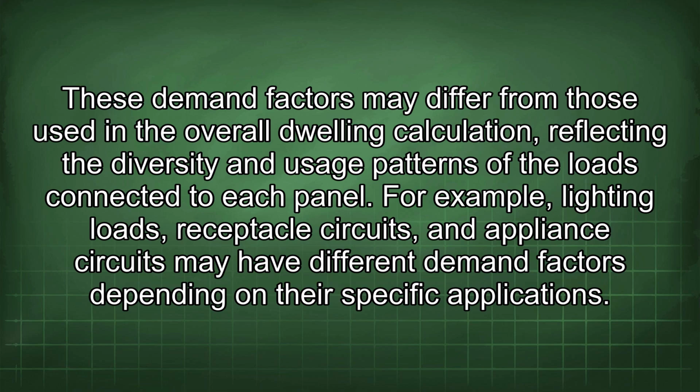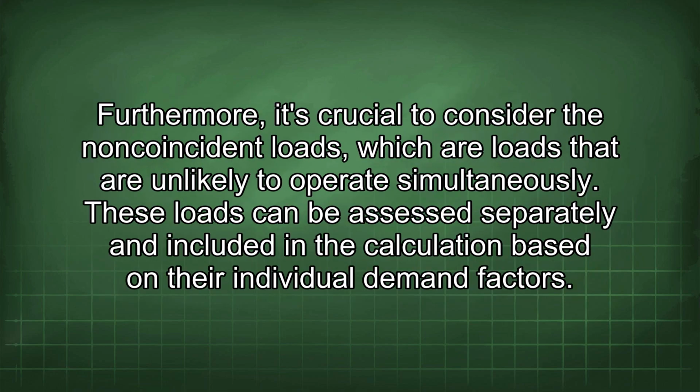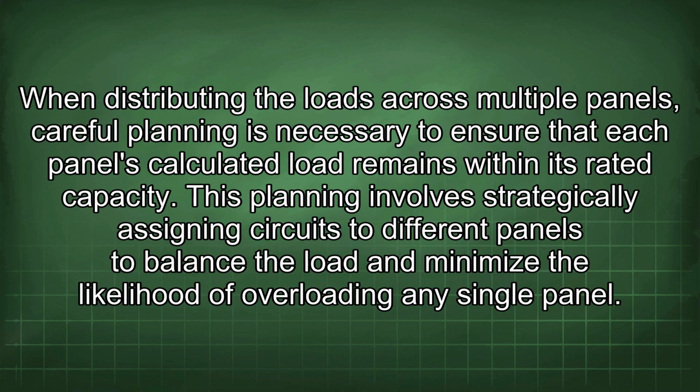For example, lighting loads, receptacle circuits, and appliance circuits may have different demand factors depending on their specific applications. Furthermore, it's crucial to consider the non-coincident loads, which are loads that are unlikely to operate simultaneously. These loads can be assessed separately and included in the calculation based on their individual demand factors. When distributing the loads across multiple panels, careful planning is necessary to ensure that each panel's calculated load remains within its rated capacity. This planning involves strategically assigning circuits to different panels to balance the load and minimize the likelihood of overloading any single panel.